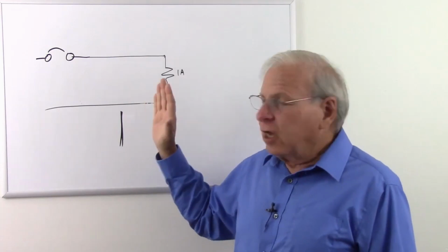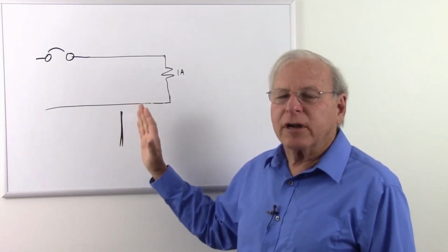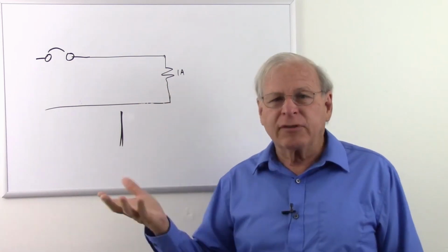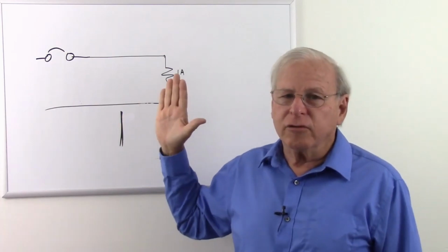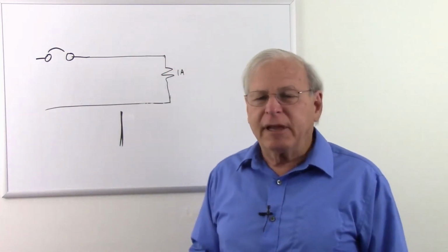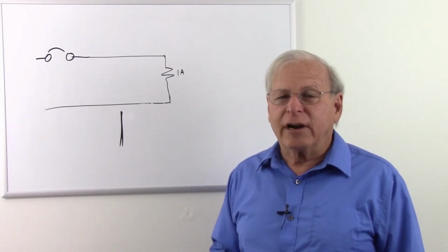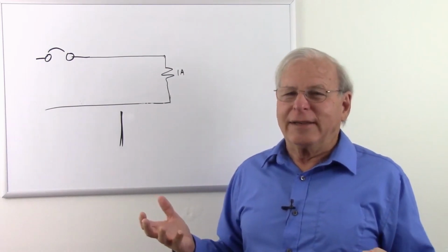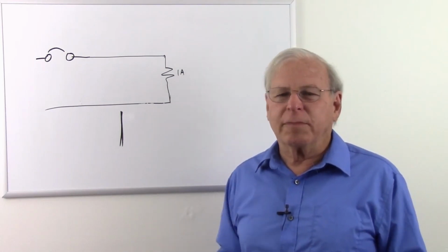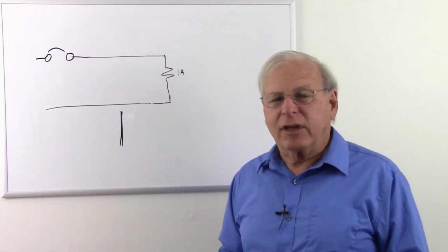One for low overcurrents that can be tolerated for a time, and some for high overcurrents that can't be tolerated. Once again, when the circuit breaker goes, you need to push it all the way off and then push it all the way back on to reset it. Another place you find circuit breakers is aircraft. You don't find fuses in aircraft because when something goes wrong, you don't want to be fiddling around trying to find a fuse and replace it. You need to fix the fault and reset the breaker immediately.